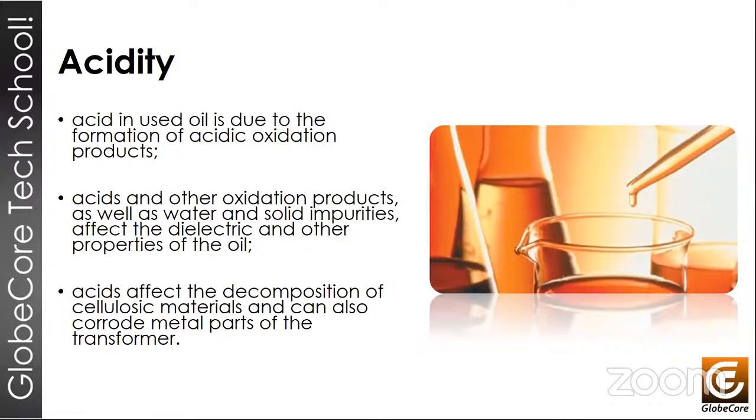So a large neutralization number will indicate the presence of certain polar compounds that will affect the electrical properties of the oil. It's very important that acids and polar compounds in the oil have some very negative effects on the transformer and the oil. With regard to the dielectric performance of the oil, we must remember that oil is a non-polar liquid, and that is its most important characteristic, because this is what makes oil a good insulator. Next slide, please.